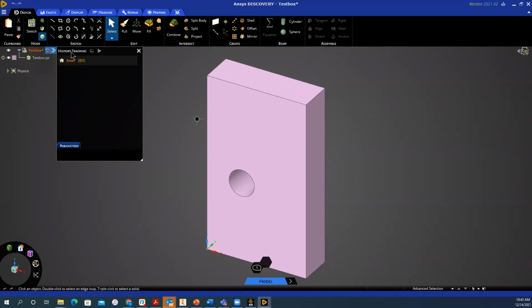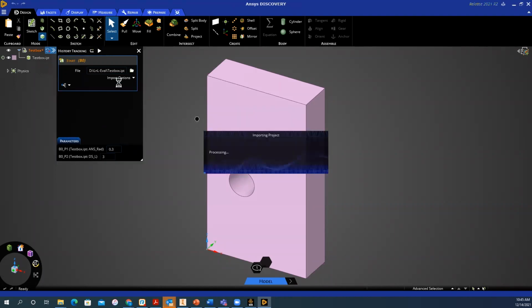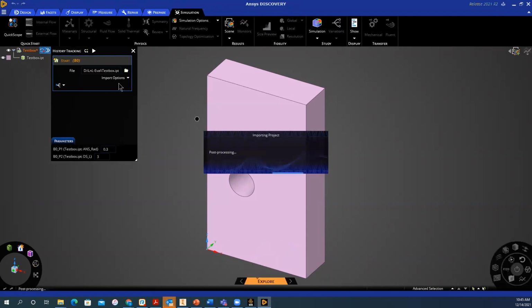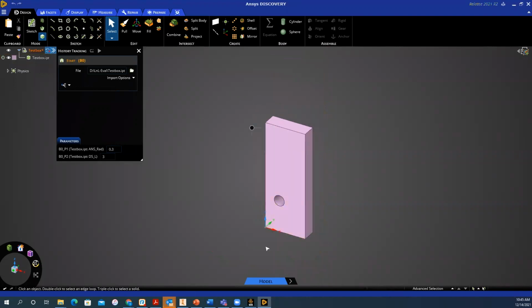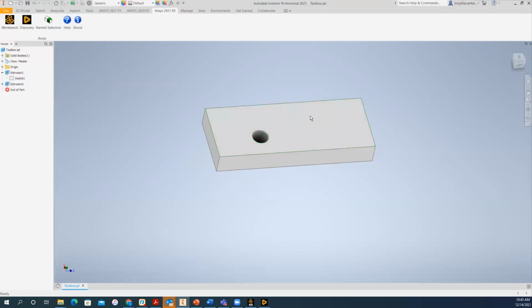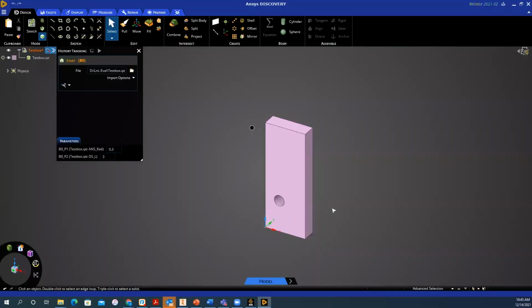as block recording. So for example, here again, if you wanted to go ahead and add these parameters, you could go ahead and do that. And then you could change the value just like you would in block recording to see what sort of modification is caused. So here also you see the same effect. And if we go back to Inventor, you will see that again, it is automatically extended because we changed it from 2 to 3. Okay, so there is no difference as such.